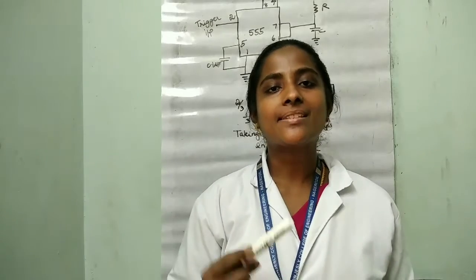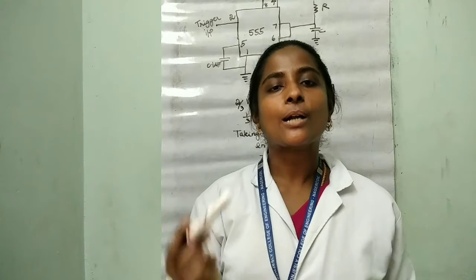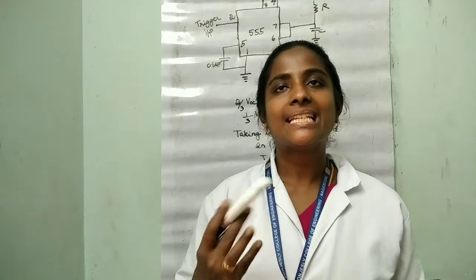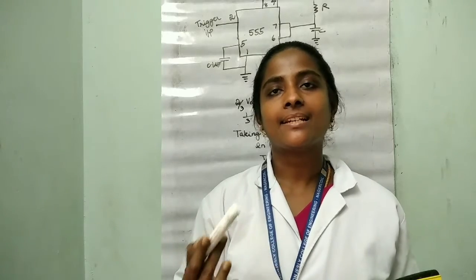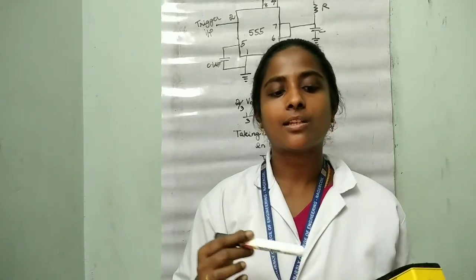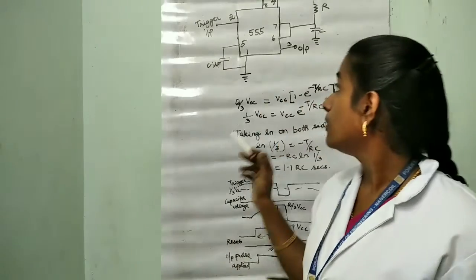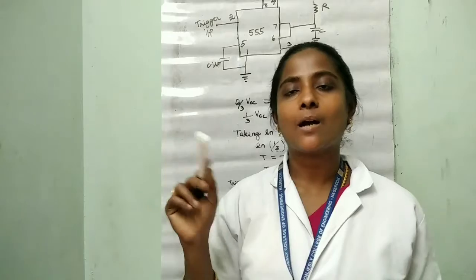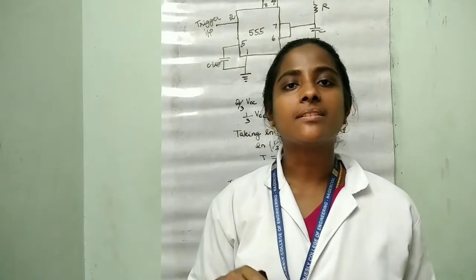Sometimes the monostable circuit mistriggers on positive edges even with the control pin bypassed by the capacitor. To prevent this, a modified circuit is used. The combination of 10 kilo ohm resistor and 0.01 microfarad capacitor at the output forms a differentiator.